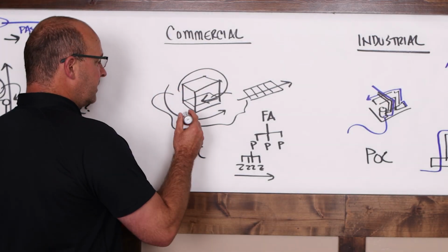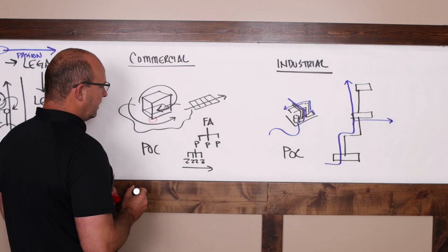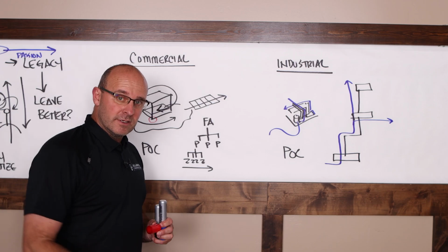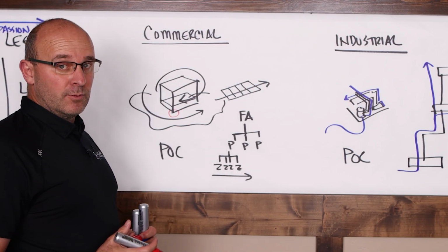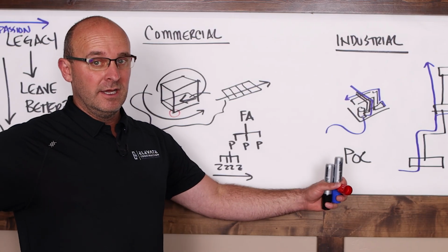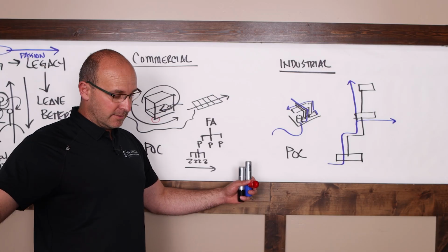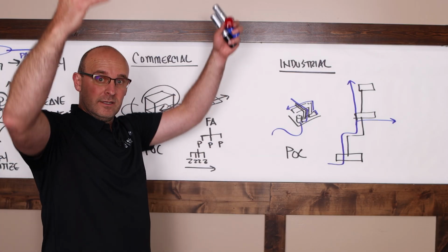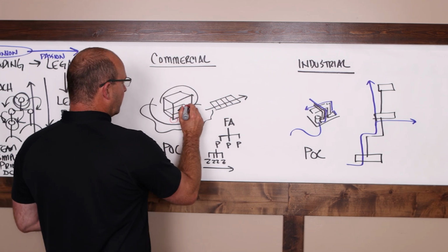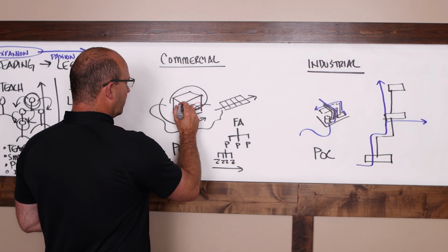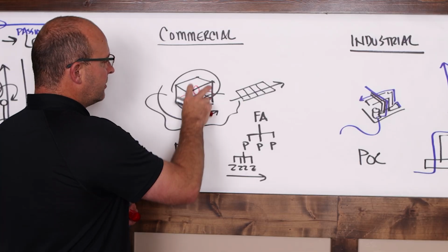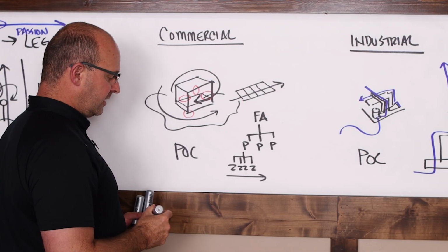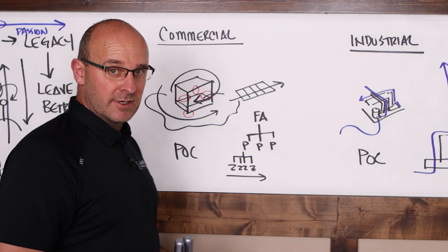So in a building, I remember a time when the underground feeders in the electrical room in the basement were a bottleneck. So we literally prefabricated everything for this under-slab electrical assembly for all of the conduit and literally craned it in place. Your overhead MEP is an easy one. Overhead corridor racks, maybe the exterior. Any of the areas that are bottlenecks in a commercial project will be considered for prefabrication.